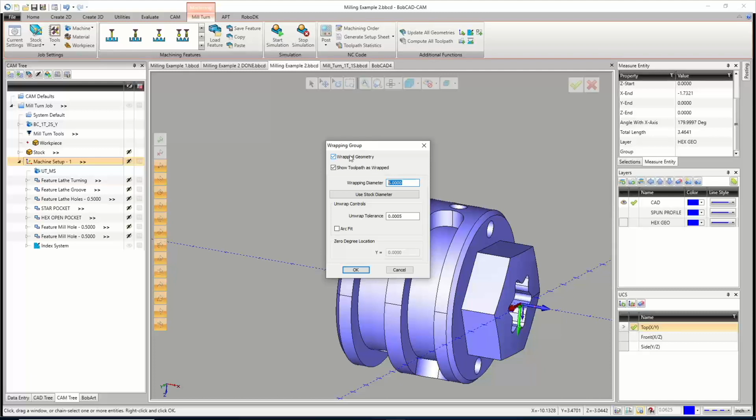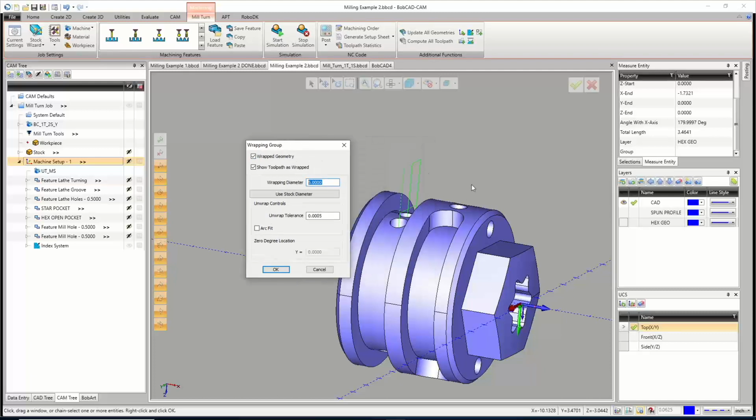The tip I'd give you for that one is make sure the geometry is drawn out at the height that you need to machine it at, or the angle that the part is sitting on it. Like, think of a pool cue's got a taper to it. If I want to wrap something around a taper, the geometry that I'm actually selecting is going to match the angle that the taper sits at. And yeah, so that's it.